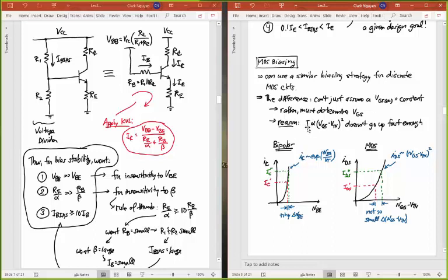And the reason is because the current for an MOS transistor, remember what it depends on? It depends on VGS minus VTN squared. And that doesn't go up fast enough that we can say that we always have the same voltage. So just compare and contrast bipolar and MOS. Remember the bipolar curve? It came up and then shot up with an almost infinite slope right here. So if I had an IC prime and an IC double prime, even though they're different currents, they pretty much have the same VBE. There's a tiny difference between the VBEs they need.